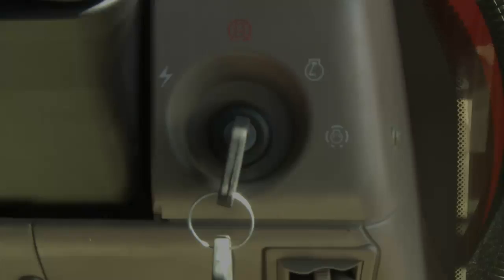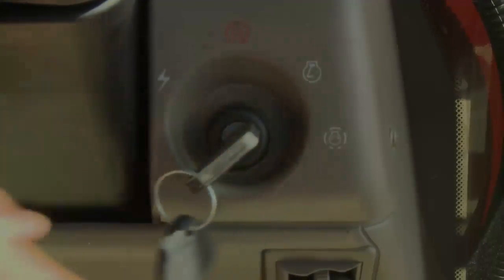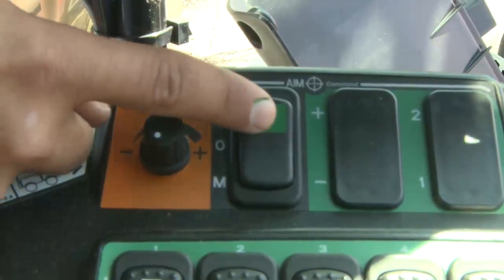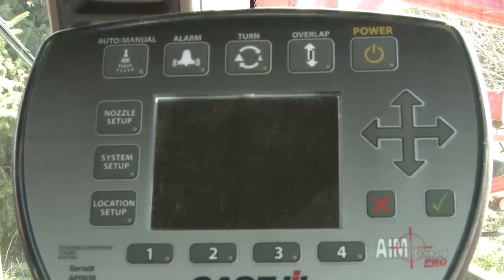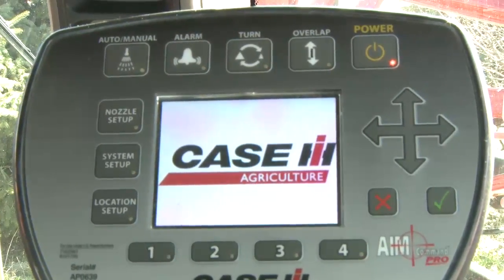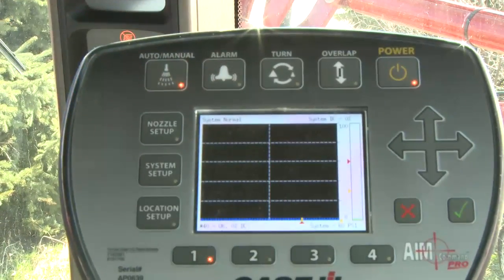To ensure consistent startup, try and do the same sequence every time. We'll turn the key and wait for the Pro 700 to boot up. Then we'll turn on the power switch that provides power, and then we can actually power the ProView display up using the power key in the top right corner. Once we've turned the pump on, we can use the auto manual switch in the top left corner of the ProView display to enable automatic pressure control.